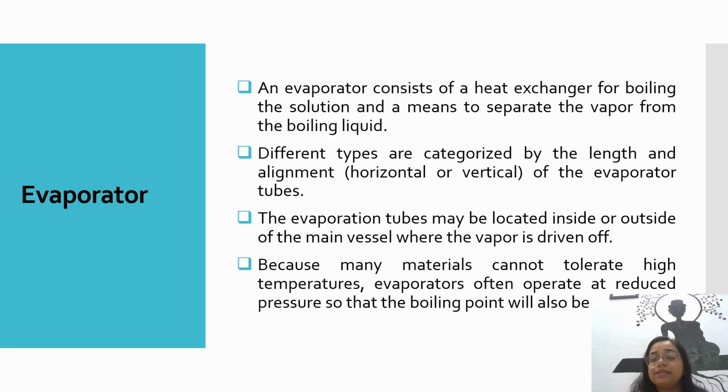The vaporization will take place, and ultimately the water will be converted to water vapor, and it will be taken out from the top of the evaporator. And as a result, as the water content decreases from the solution mixture, the concentration of the solute in the evaporator ultimately starts to increase, and the given steam is ultimately collected as the condensate after the process.